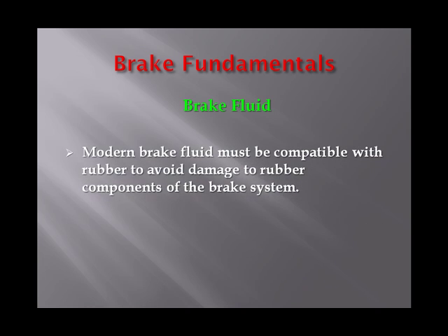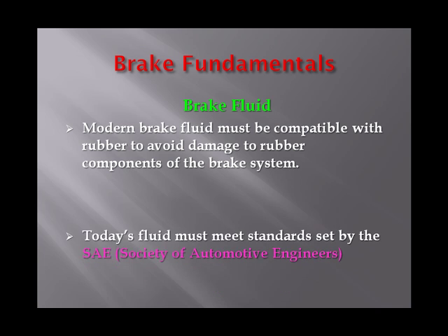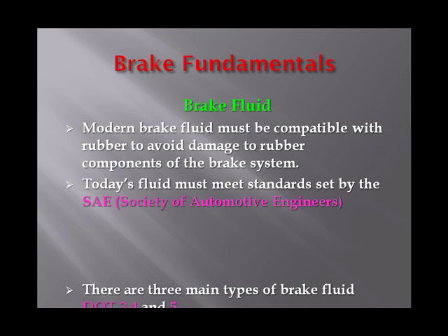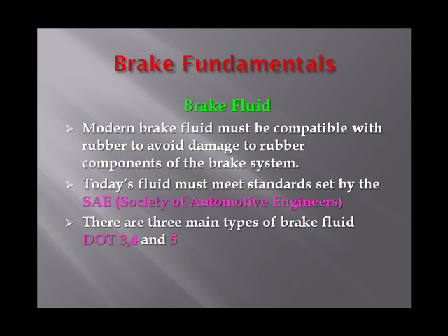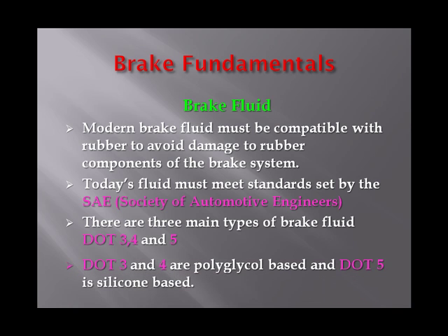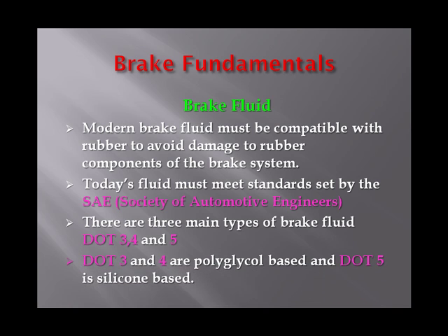Brake fluid. Modern brake fluid must be compatible with rubber to avoid damage to rubber components in the braking system. Today's fluid must meet standards set by the Society of Automotive Engineers, SAE, and the Department of Transportation, DOT. There are three main types of brake fluid: DOT3, DOT4, and DOT5. DOT5 is a synthetic brake fluid, while DOT3 and 4 are polyglycol based, similar to engine coolant.